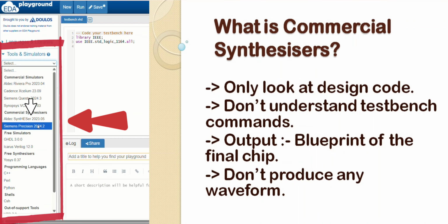These tools build your final hardware. They only look at your design code, like this design.vhd you can see here. Okay, they cannot understand most test bench commands like wait or anything else.